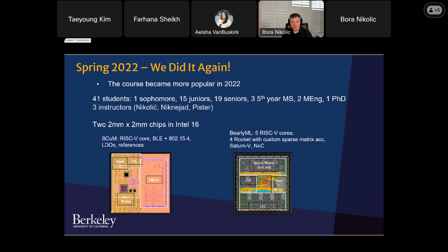technologies, including the 28, and we had to switch that technology to Intel. Intel came forward actually with a donation of the test chips in their 16 nanometer class technology. Now keep in mind, 16 nanometer technology is a FinFET technology. It has more complicated design rules. It is a little bit more challenging, or significantly more challenging, to get to design closure in that process than in TSMC 28. But nevertheless, we had a success.